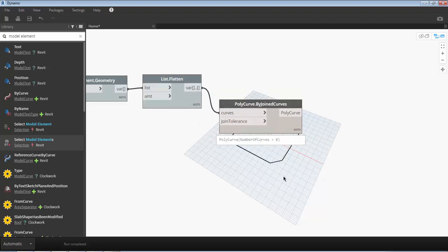We need a number of stories, or a building height, to be defined before creating a 3D element. We need curve profiles, so we have to transform the element to different heights or different intervals. It's a geometry transformation, so we need the Geometry.Transform node.